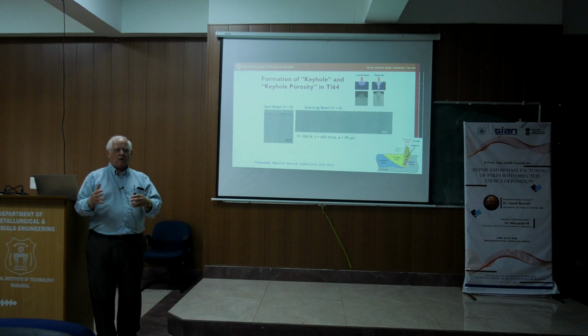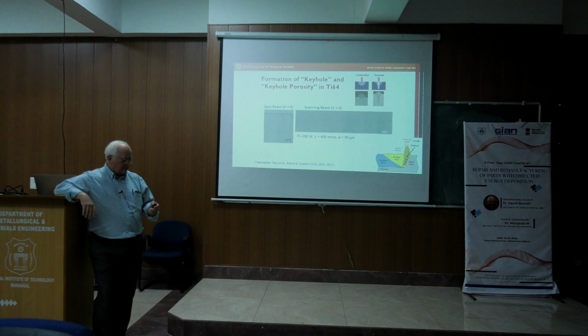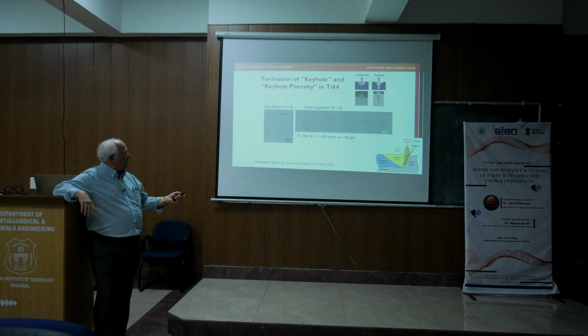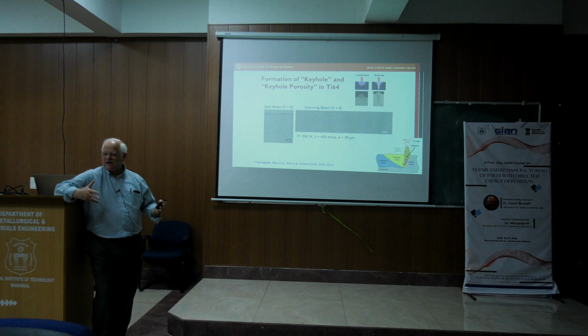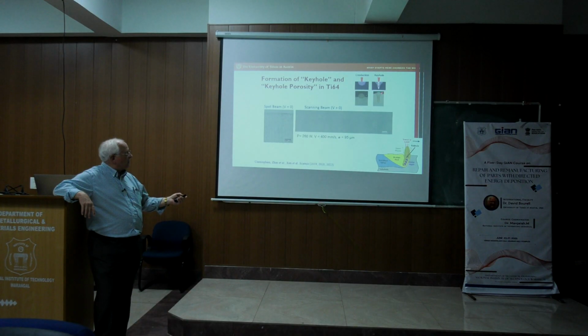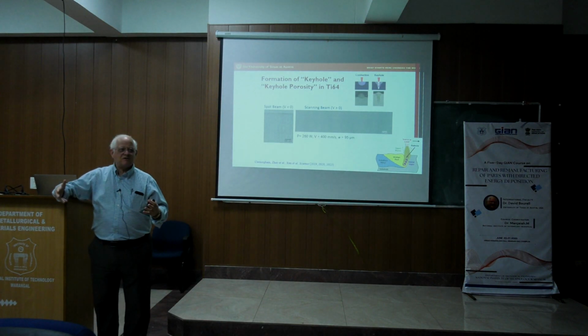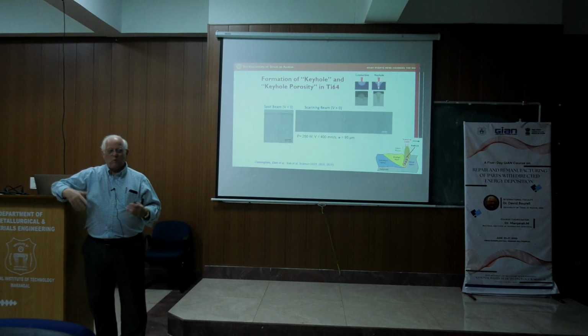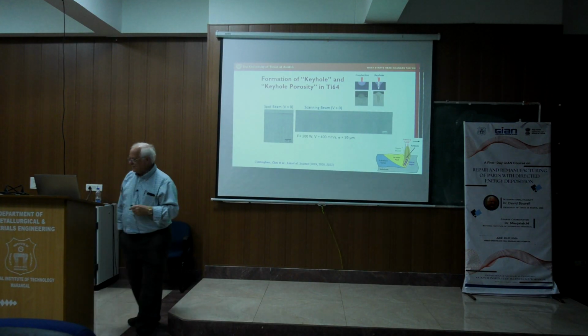Basically, the laser will interact energetically with the plasma, and the result is that it increases the heat transfer in a way that we can produce a really deep hole. So for laser drilling, keyholing is just a way of life. What you see here is a very deep fusion zone that we get from keyholing. But we don't normally have porosity from keyholing, though we do with additive manufacturing. That's the following observation we have to make.